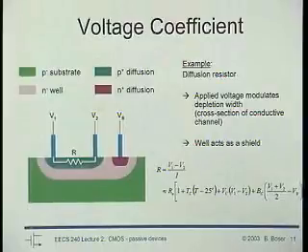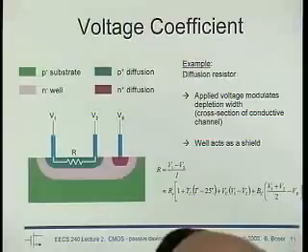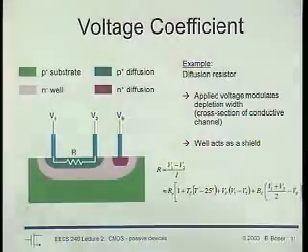Heck, if these carriers end up in our signal, ooh, not good, right? So we want to shield our circuits, and our signals more specifically, from this substrate, right? Of course, we're going to put all sorts of contacts in the substrate, and the digital stuff, you go way over there, and the analog stuff is over there, and so on. But nevertheless, we take our precautions.